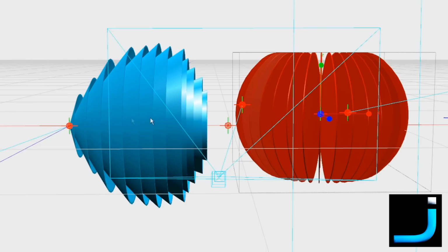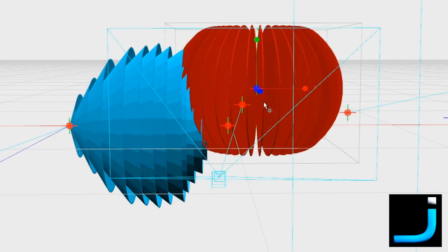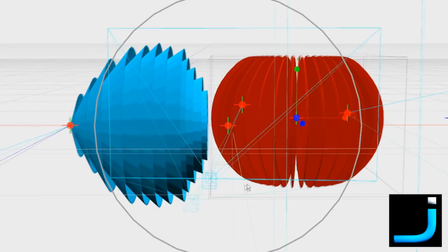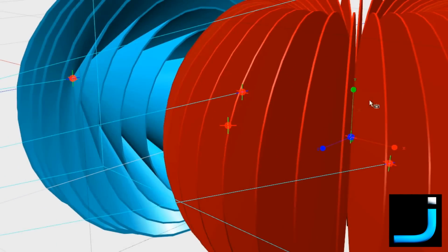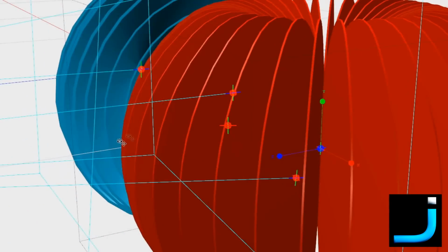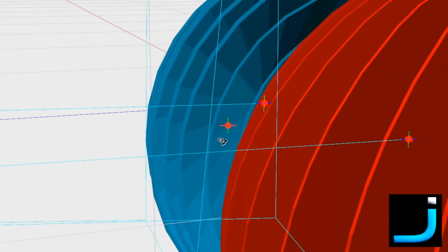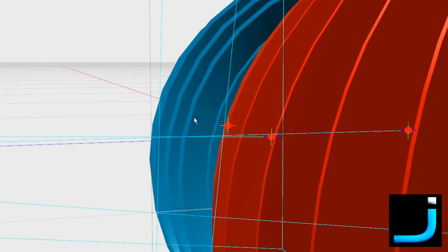And the great thing is that with a circularly polarized antenna, because of the way it works, you're never going to get less than 3 decibel loss, no matter what your orientation is on the plane. I mean, if we look at the actual cross-sectional view here, when you look sort of directly at the circular antenna, yeah, this area here is almost like a vertical cross section, as is from the top.